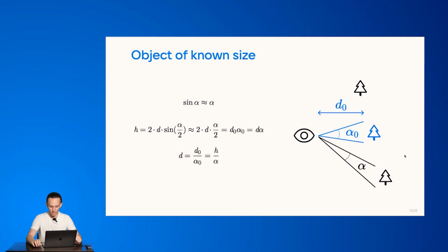But we are mostly interested in the world coordinates that are measured in meters, because we want the robot to, let's say, approach the ball and kick it. Knowing how exactly the image formation works allows us to perform some procedures more or less in the backward order, so that given the pixel coordinates of the objects, we can find out their real geometrical coordinates in the scene that we are filming.